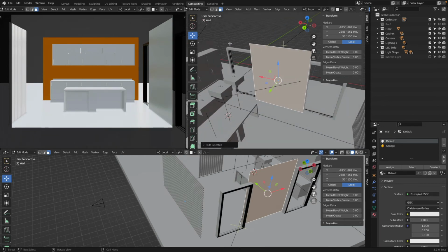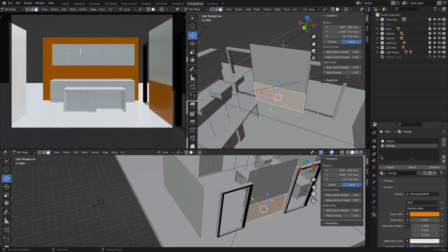Then I turn on this cutting tool via K like knife. Pick a height, maybe down here. And I can press X. This goes along the X-axis. Click and enter. And you see now I have two faces. Okay. Here I have this material already added because this whole geometry, we added this orange material, but I didn't assign this yet. Assign, there we are.